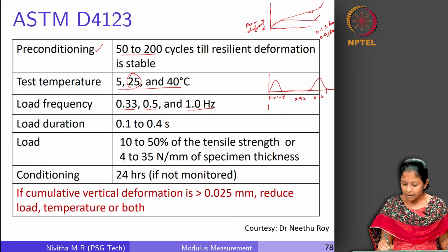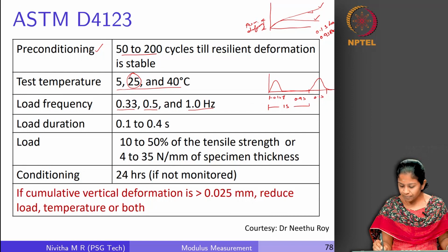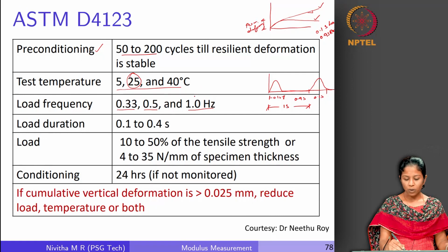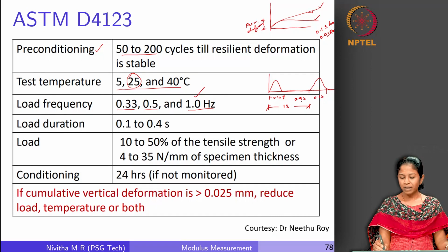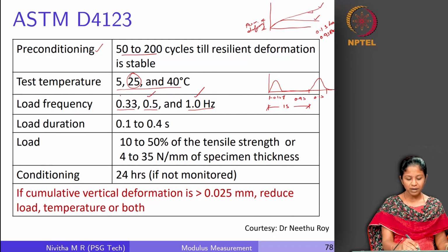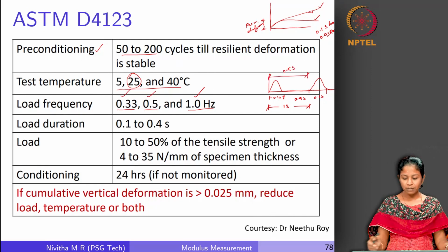So, one load cycle is going to take us 1 second. So, the number of cycles I apply per second is 1. So, it is of 1 hertz frequency, right. Similarly, we can have different loading times. We can reduce this loading time and appropriately proportion the loading and the recovery period to get different frequencies. So, this is with regard to the frequency of testing.